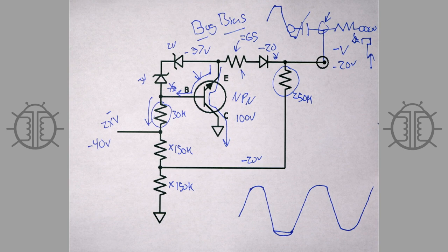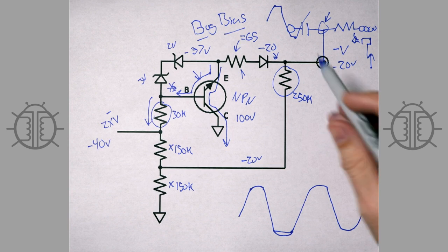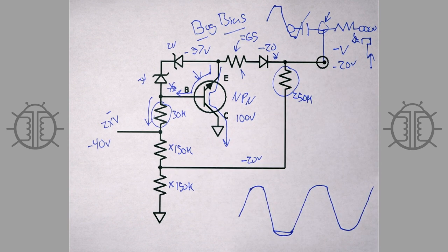Now, if you're saying, well, just don't ever clip your amp. Well, yeah, that's great. Have really efficient speakers and listen close, and have an amplifier that's really powerful. But if you've got a tube amp that's 10 watts per channel, and you've got medium efficiency speakers in a medium-sized room, and you're listening to orchestral music, you're going to clip the amp occasionally, and its recovery characteristic when it clips is going to determine how those clip transients sound to you when you're listening to music. And that's why this thing is cool. So anyway, that's it. Bug bias.